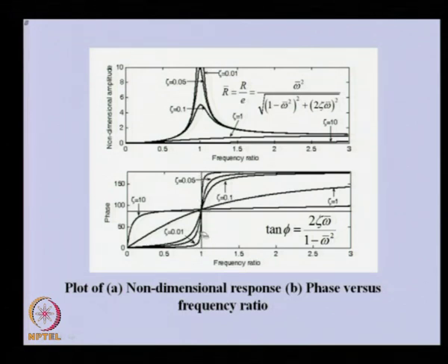You can see of the order of 180 degree. The meaning of that is the response changes its phase with respect to the force, and there is a change of 180 degree. That means the unbalanced force which was outside becomes inside, toward the center of rotation of the shaft, and because of that it tries to pull the rotor toward the bearing axis, and because of that we have smaller displacements as we are going toward the high frequencies.